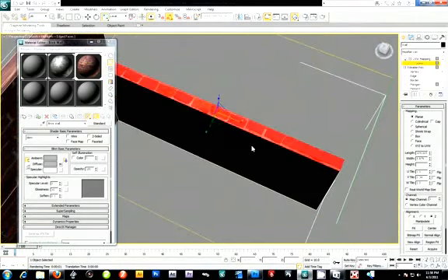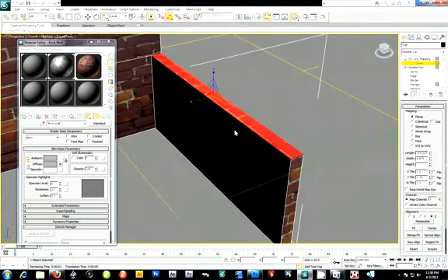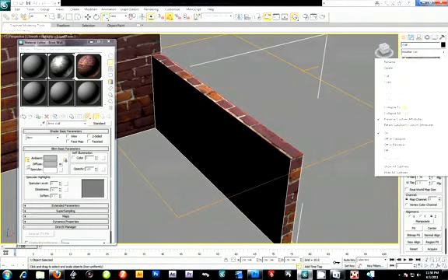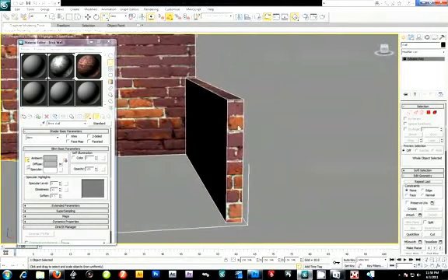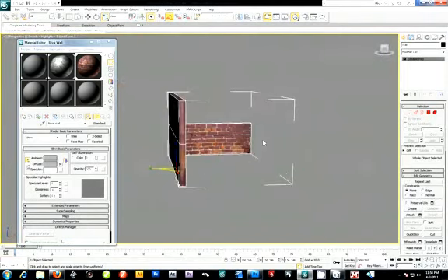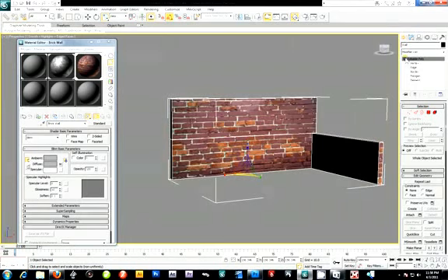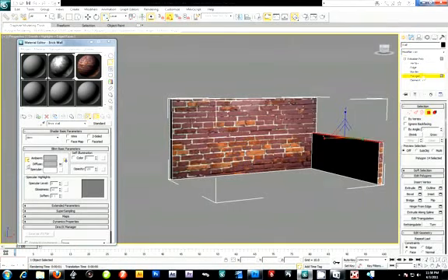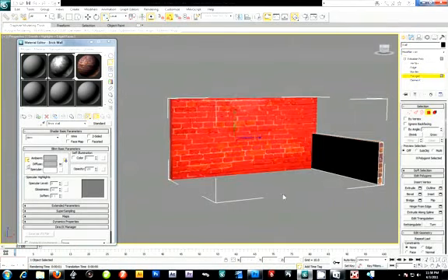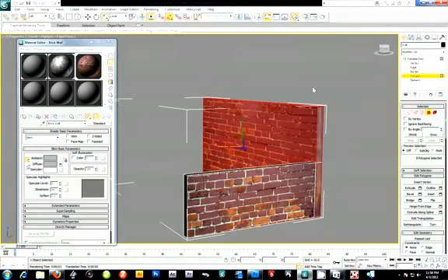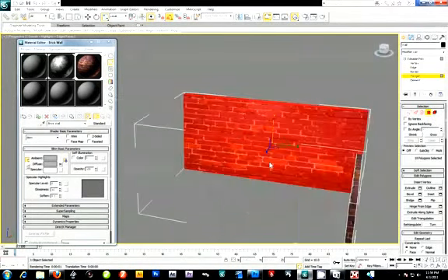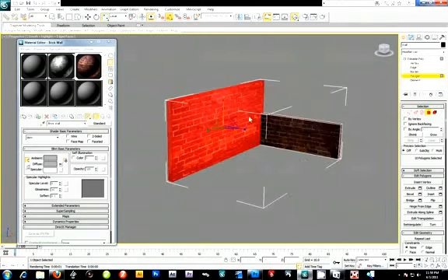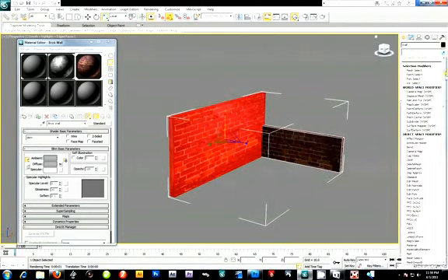And then I'm going to click on top of the stack, right click, collapse to, and hit yes, and now that locks it in place. Now we can fix the other parts. Alright, so I can actually go back to the polygon mode. I'm going to select this side now, and we'll worry about this side later right here. Actually, we can probably grab those two, and I'm hitting control. Alright, so I'm going to go ahead and go UV map, because we got to remap that.